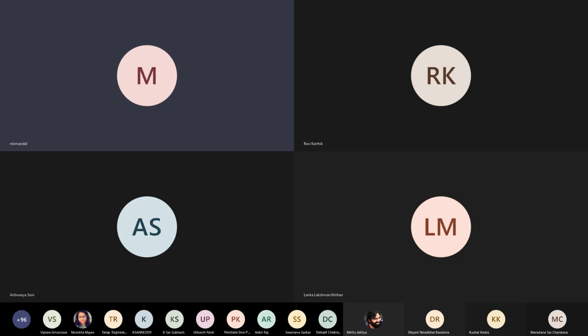So here usually what we do, we put two metal vias. These are metal vias which start from the top wall and connect to the bottommost wall. So in the cross-sectional plane, this is how it looks: the metal via goes from top to bottom, top to bottom. So this is basically a metal wire inserted inside the waveguide, and that provides shunt inductance.